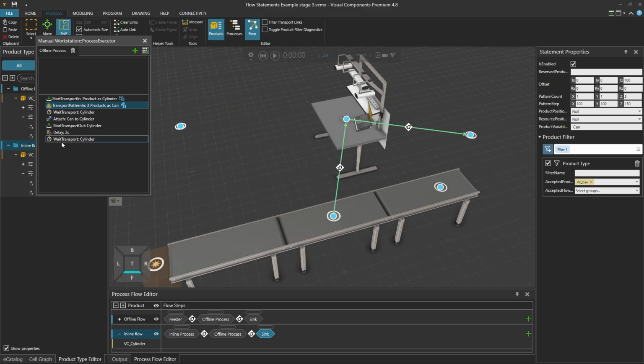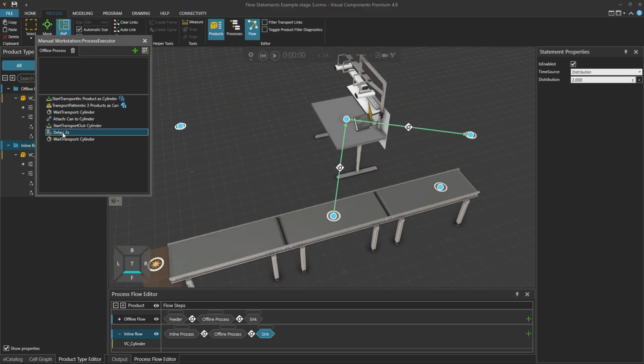And resetting the simulation, as an example, in machinery, there could be, for example, a door opening or closing, while the next product starts to enter a process. Or we could say, start transport out of a product from a machine. And then there is some machine process that needs to be done anyway, but it is done parallel to the transportation event. So we may have a transport out. We may have a machine process that takes 10 seconds. Then we just check that the product has actually left, and then the machine can start its cycle from the beginning.